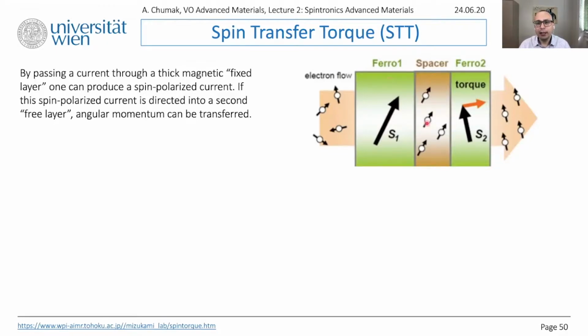layer. And we also know that the spin polarized current will propagate only a certain distance, named spin diffusion length. If you are taking a point as large and far away from the interface as the spin diffusion length, then most likely there was a spin flip scattering event, and it means that your spin polarization disappears. Therefore, in the structure when we study spin transfer torque, we are using a thickness of the spacer smaller than the spin diffusion length, because we want this current to reach the second ferromagnetic layer in the spin polarized form.